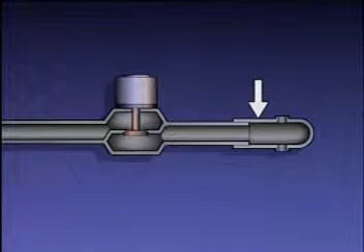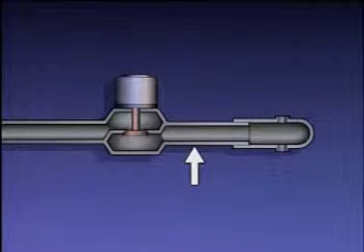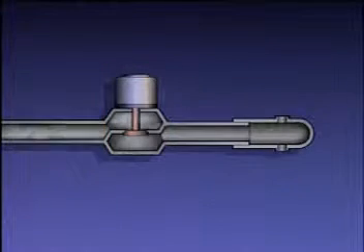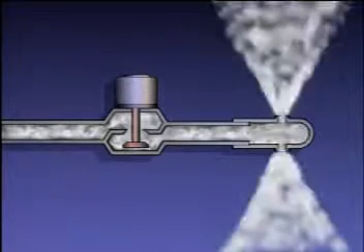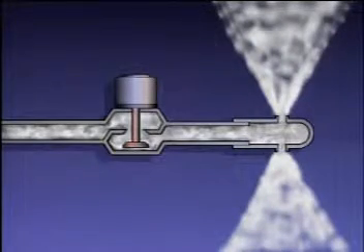During the operation of most boilers, especially coal-fired boilers, soot builds up on water wall tubes and other components. This soot buildup blocks efficient heat transfer, and it must be removed if efficient boiler operation is to be maintained. Soot blowers remove soot by blowing it off of the tubes with a medium such as compressed air or steam. A typical soot blower is made up of a lance tube with nozzles, a feed tube, and a valve. When the valve is open, a blowing medium is sent through the feed tube under pressure and discharged through the nozzles in the lance tube.